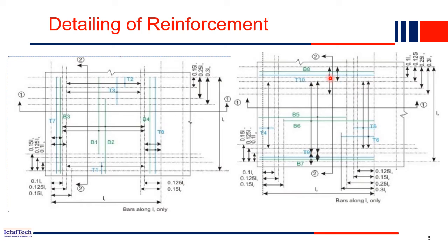That's why when you visit a slab next time, before casting, after the reinforcement is done, then you will find this type of grid in a slab. And now you understood why these bars are provided and how many bars minimum have to be provided, all these parameters are mentioned, and what will be the spacing. So some bars will be continued. For example, if you see this B2 bar, so B2 bar will go from here up to here. So after some portion, we have to curtail it, we have to cut it out.